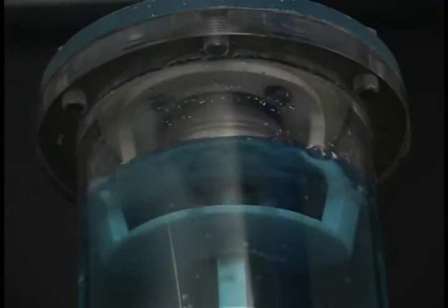All Valmatic air valve floats are manufactured with heavy-duty Type 316 stainless steel, and all floats are guaranteed for the life of the valve. Air vacuum valves are available in sizes 1/2 inch through 20 inch and have inlets and outlets of the same diameter.